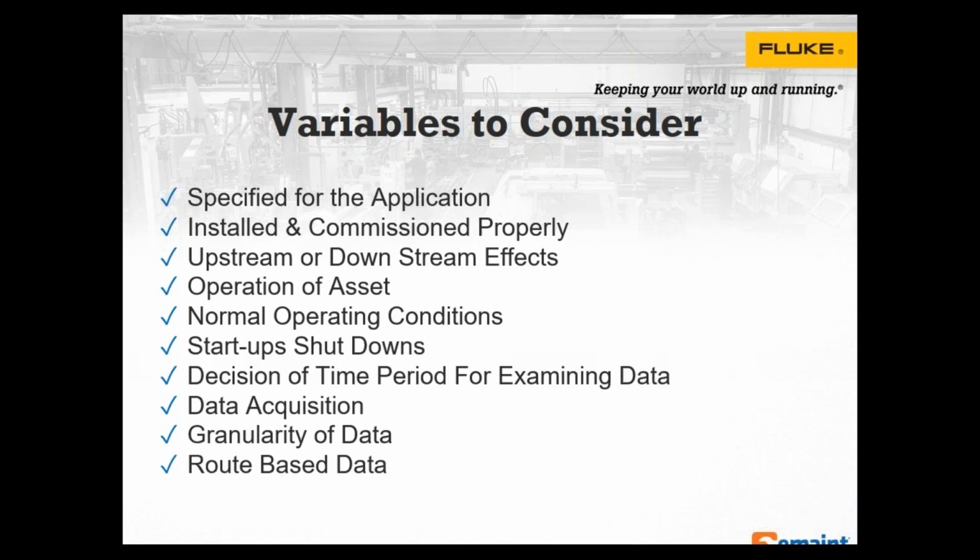Obviously, there's always the human error aspect of things, and things to consider about the actual training of the operator themselves. Are they touching the same point? If they're doing a vibration reading on a motor, for instance, checking the bearing, are they checking the same spot every time? It's good to be consistent.